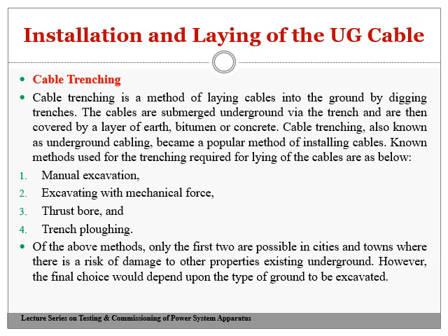The cable trenching. A cable trenching is a method of laying a cable into the ground. As we have discussed the laying of the cable in the previous class, once knowing which method is to be followed, whether the direct method, or drawing system, or solid system, for all those things we require trenching. Therefore, cable trenching is a method of laying cables in the ground by digging trenches. It depends upon the standard, and upon the capacity of the cable.